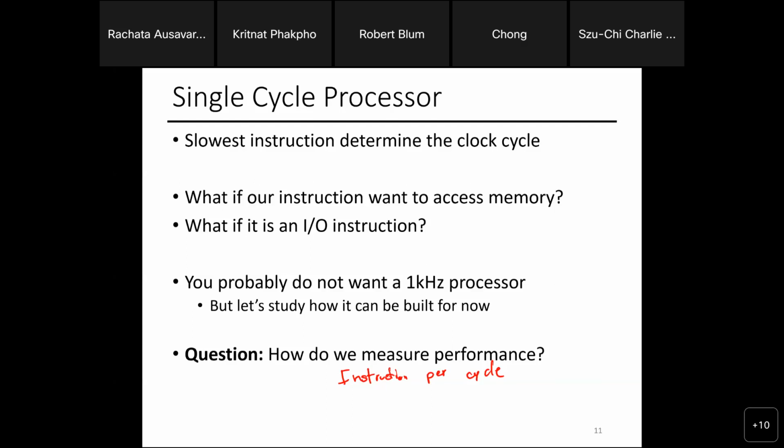Yeah, so usually back in the day, we would use a unit called cycles per instruction to measure the CPU performance. If I want to finish, on average for all the instructions that I run, how many cycles does it take per instruction? It turns out we made the CPU fast enough that these days in one cycle, we actually finish a ton. So we just flip the denominator and numerator. It becomes instructions per cycle. If you look at CPUs these days, it's usually greater than one in most cases.